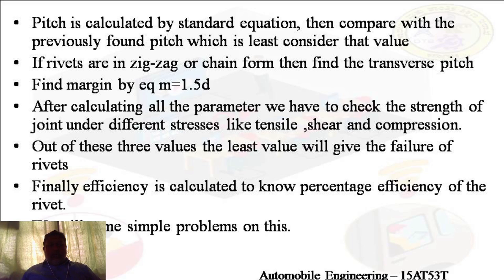After calculating all the parameters, we have to compare them with the stresses available to see whether the design is feasible or unfeasible for that particular dimension. We generally have 3 formulas, on the basis of tensile, shearing and compressive or crushing.